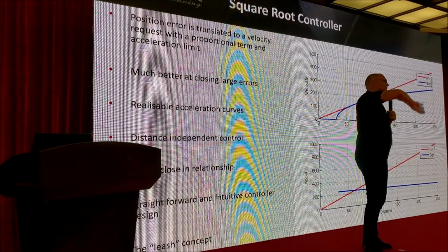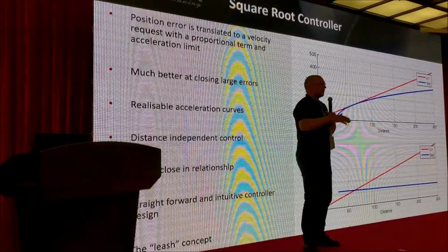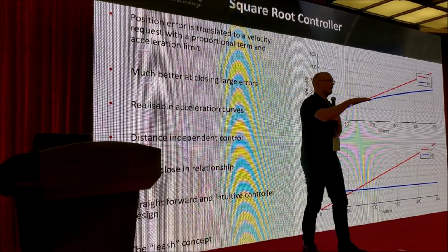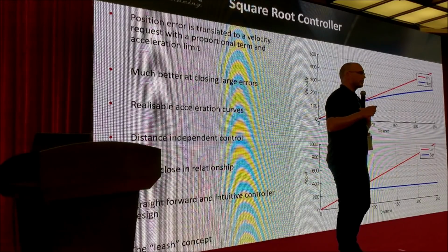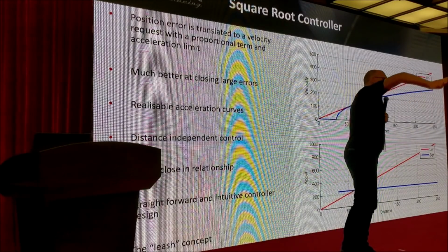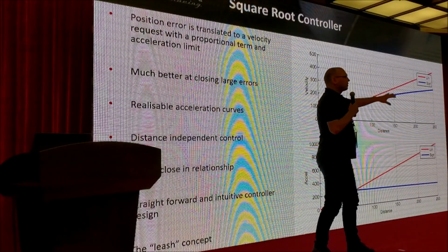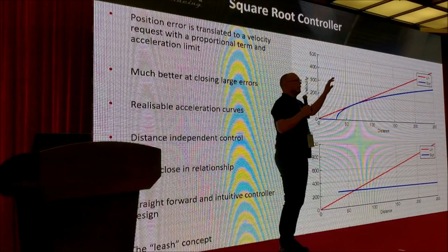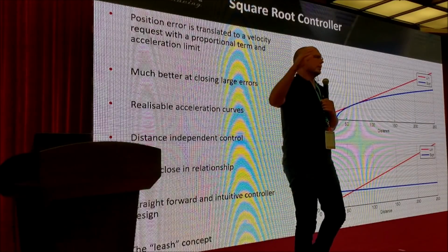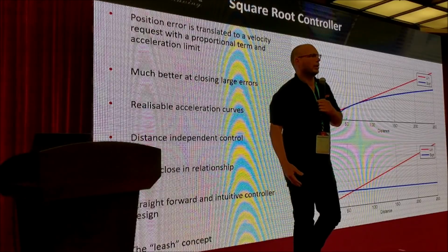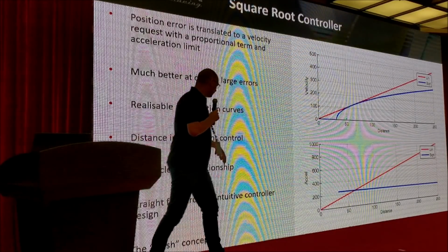And that's where you get these massive overshoots, and aircraft that flew perfectly well for a while, when all of a sudden they got disturbed, went boom, boom, boom, boom, and went into the ground. So this square root controller directly understands that there is a limit to how much correction an aircraft is able to provide, and it deals with that at the highest level.